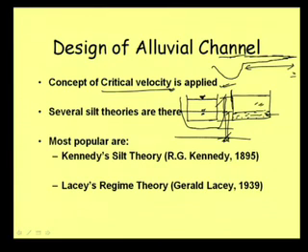So head is coming down, and when the channel is expanding, the velocity will also drop. So this v square by 2g portion is also dropping. So total head is reducing, and when you have less head, it can flow up to a lesser extent. So the command of the canal is reducing. Command means the distance or the area that can be covered by a particular canal, and it is called the command area of the canal.